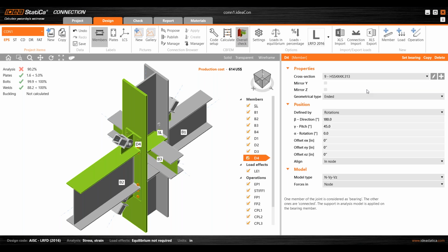Yeah, so as far as an actual oversized hole element, there is not in version 22. We do have some workarounds in that you can adjust the bolt assemblies when you get into the materials tab in the software. You can basically copy a bolt assembly and adjust the actual size of the hole that's being punched for that bolt size. So you can create your own bolt assembly for the oversized hole at this point.